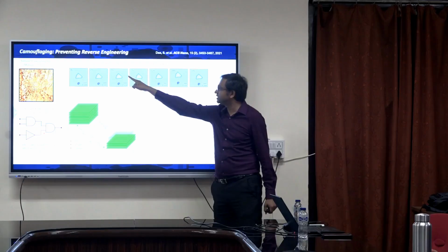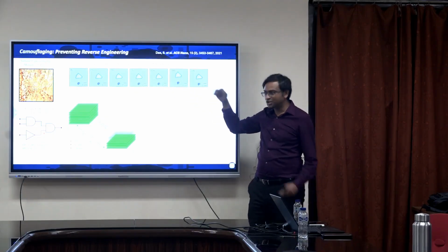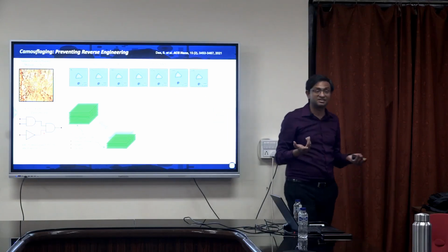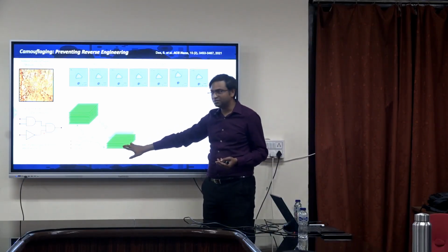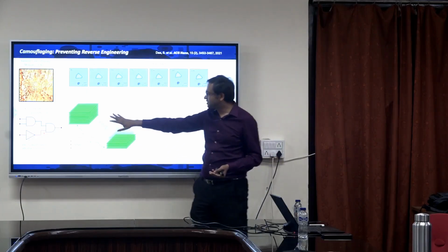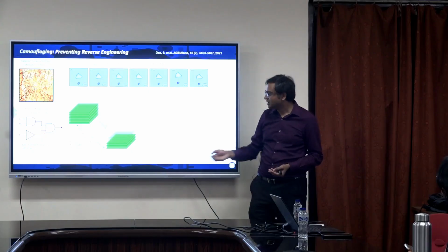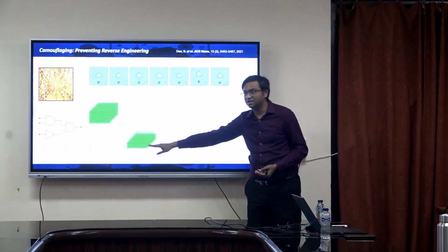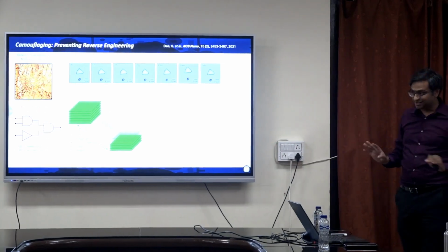So what am I doing? You see 15 seconds, 30 seconds. Remember this timestamp? We are literally doing oxygen plasma. So on top of it now there is an oxide layer which is transparent. So the optical appearance of the flake does not change. But now this material on the top converts the bottom material into P-type. It just dopes it. This is the surface charge transfer doping that we spoke about. So although we started with an N-type material, it has become a P-type material because of this unique property of 2D material, where the oxide is, number one, transparent and, number two, serves as a P-type dopant for the underlying material. So I have now camouflaged the function of the material without changing its appearance.